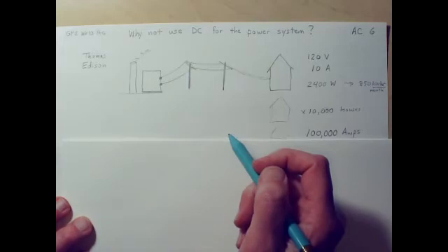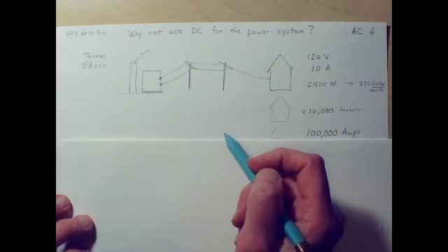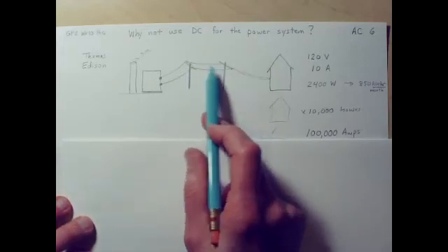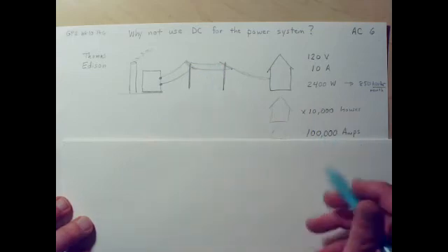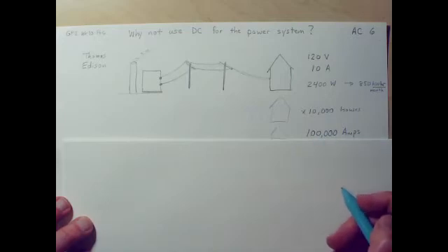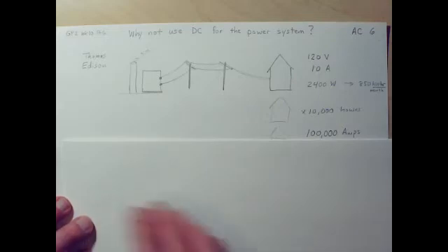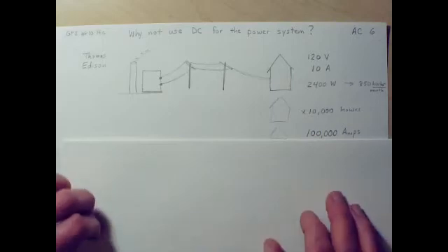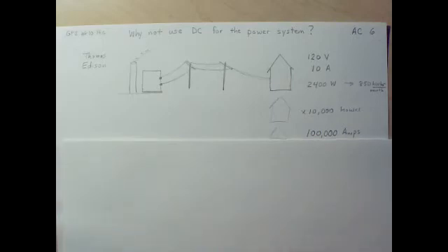And if it's any distance away from the city, or from most of the houses for that matter, many of these wires have to carry currents on that order, 10,000 amps. What size wire would that require, you might wonder? You probably don't have much familiarity with wire. In your house, you have something like 12 or 14 gauge wiring in various places, and that's intended to carry 15 or 20 amps of current.